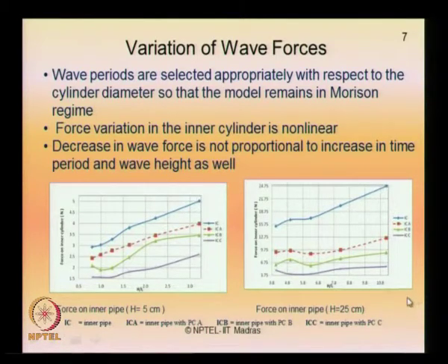In both cases, one is for the extreme wave height of 25 centimeter, the other for the lower extreme value of 5 centimeter. In both cases you will see there is a force variation in the inner cylinder with the different outer covers, and this seems to be non-linear. You can also see that the decrease in the wave force is not proportional to the increase in time period and the wave height as well.